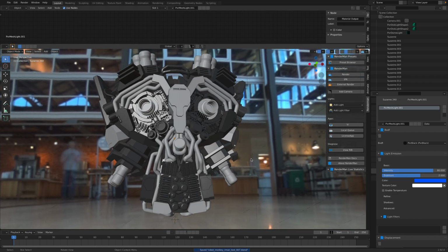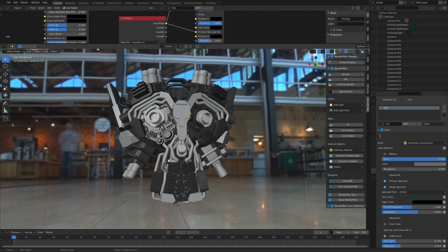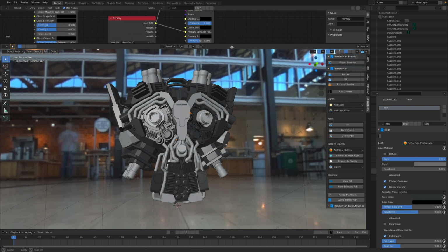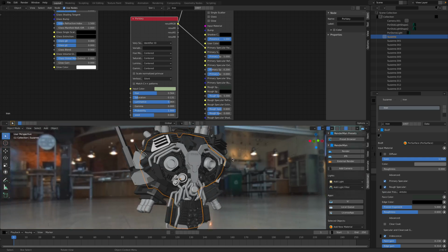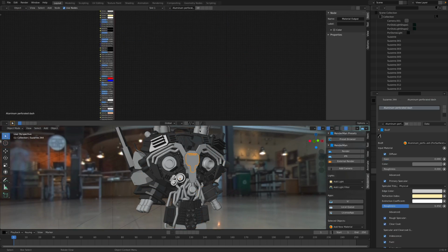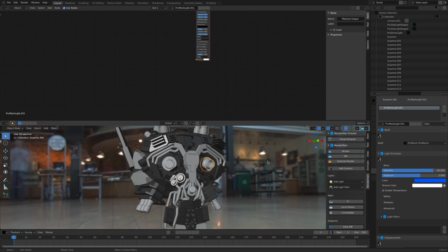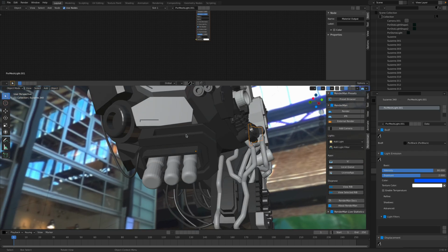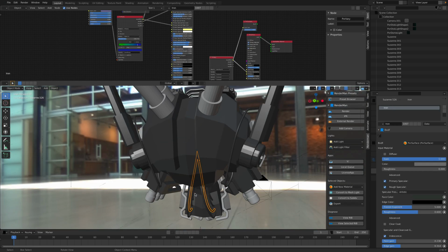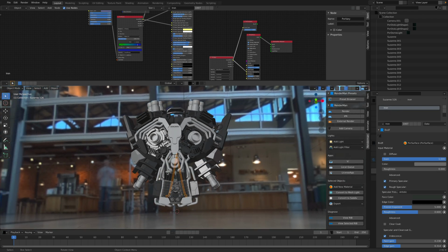Okay, so that's pretty much what I want to talk about. Yeah, we can use PxrVary nodes to randomize the color of every object. If you are separating every object, that's not wrong, but you're going to have to deal with a lot of objects. If it's becoming a single asset, it doesn't matter anyway. If you want this as a single object, you can still make the cycles random per island. That can also work, and use that. Things like the cable here, I want to use a different color. Maybe I'll do that in my own time.